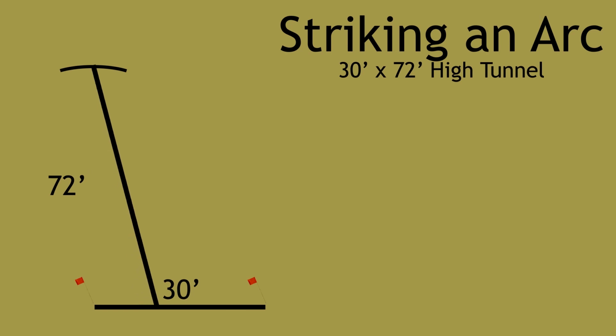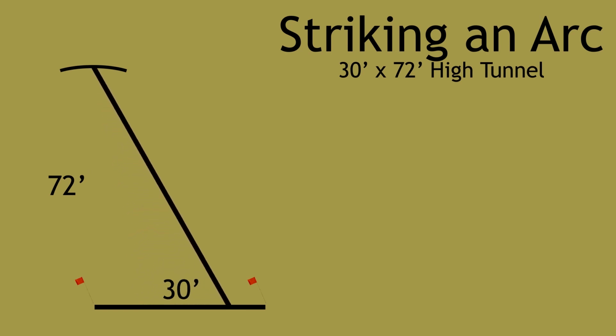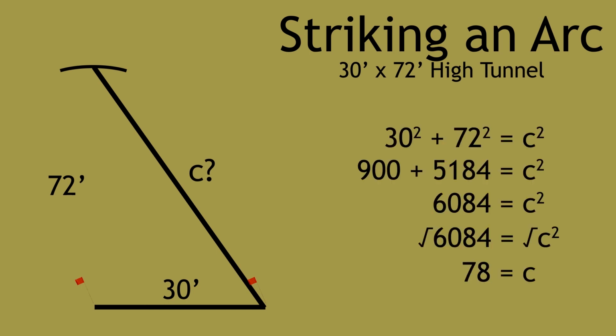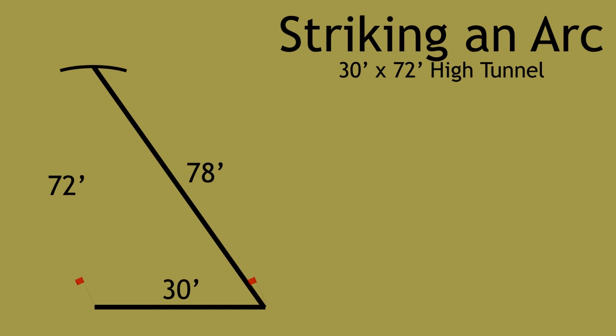Now, move from the starting corner across the width to the other corner. Keep the other end of the measuring tape at the other corner. You will need to calculate the diagonal measurement before proceeding. Use the previous formula to find it. Measure this diagonal and strike an arc. The corner's correct location is at the intersection of these two arcs.